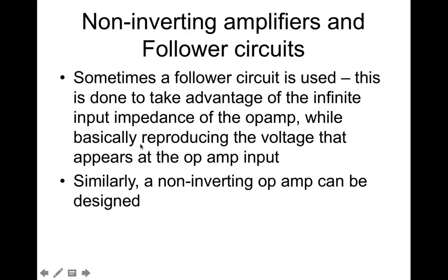Now, sometimes we want an amplifier that doesn't invert. Usually that occurs if you are concerned about the phase of the signal, because when you invert, you introduce a 180-degree phase shift. And sometimes, for various reasons, you don't want that. Most of the time, in biomedical signal processing, you are not trying to reconstruct a signal, you're just trying to analyze it and pull data out. So you often don't need the phase, but should you need to preserve it, you might want to not have that 180-degree phase shift.